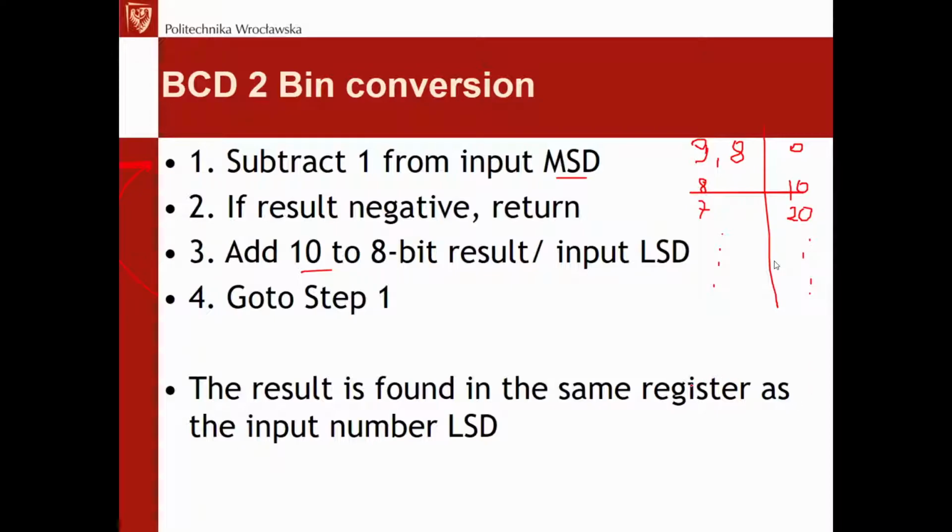Of course, in case of the algorithm with multiplication and division, this time no division is necessary. Therefore, this conversion, the BCD to binary, is simpler, because then it is enough for us naturally to take the MSD, multiply it by 10, and add the LSD, the 8, and then we have the binary 98. That's the conversion with the non-iterative method. So here actually this is much more realistic, because it's usually faster than the iterative algorithm.